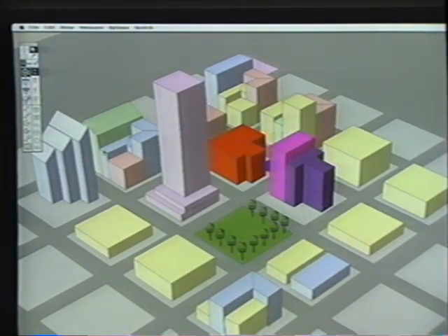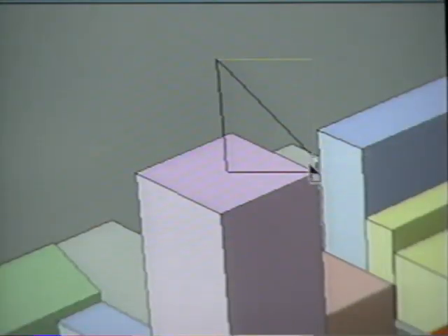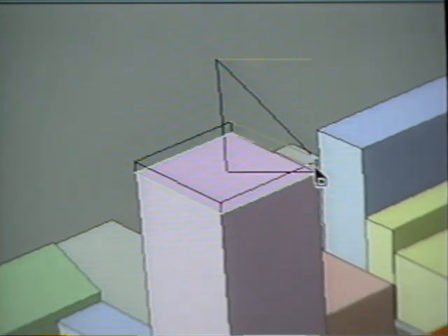To add our new element to this drawing, we'll select the Wall tool. Choose the ground plane by clicking on it. Click and drag for a height of the pyramid. Then select the corner parts to enclose the shape, clicking at each corner point. When you complete the shape, the program shades it with a color which I've pre-selected.